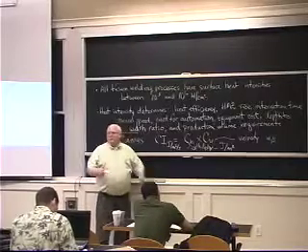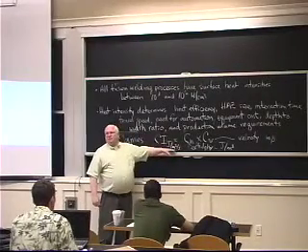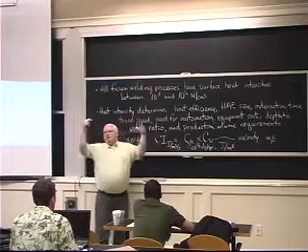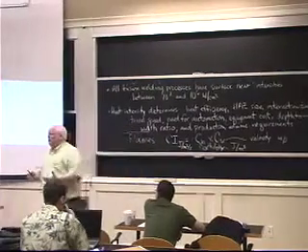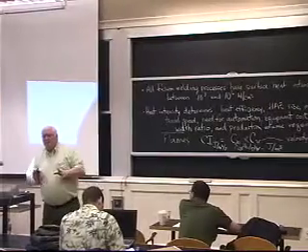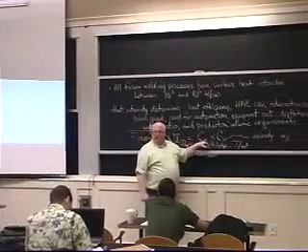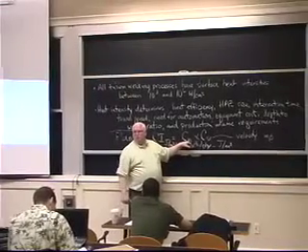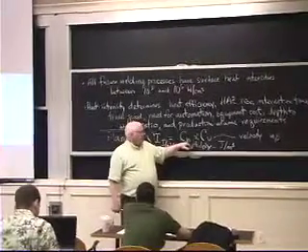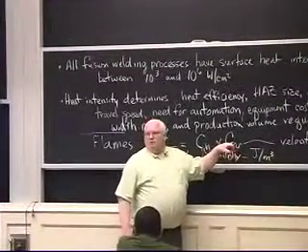If you go to the boiler business, they talk about a combustion intensity which is not a surface heat flux. They'll talk about a combustion intensity in terms of per unit volume, because you're talking about the volume of heat in the boiler. They define it a little bit differently, but it's basically the same thing. There's an enthalpy of the reaction, how much chemical energy is being released by burning the fuel, and different fuels have different enthalpies. And what's the speed of burning?